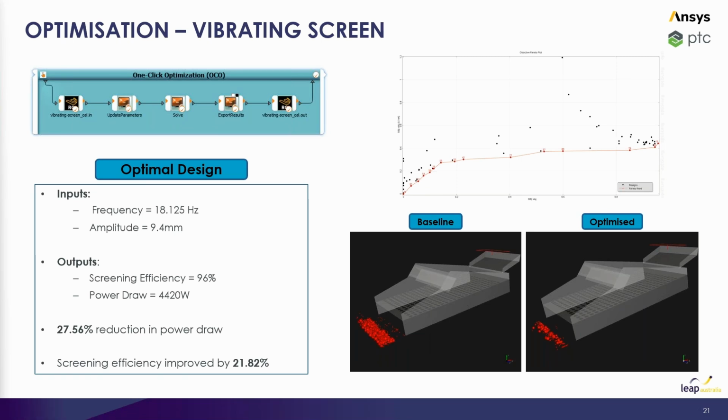So what we can do with the optimization tool is generate this kind of plot. This is a Pareto plot showing a Pareto front, which represents essentially the set of points which cannot be improved on for any objective without degrading or sacrificing at least one other objective. Effectively, how we can interpret this data is that it's a boundary defining the trade-offs between conflicting design objectives.